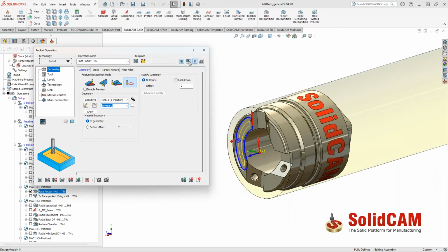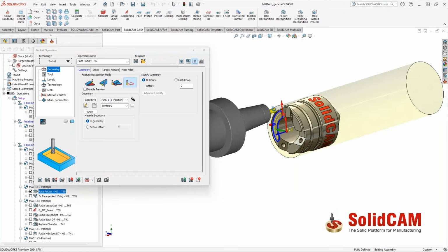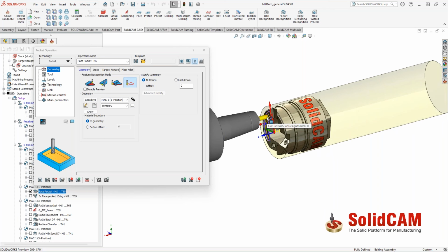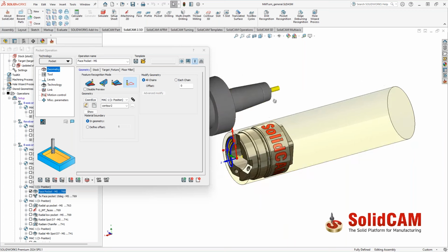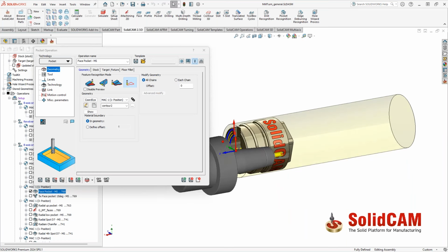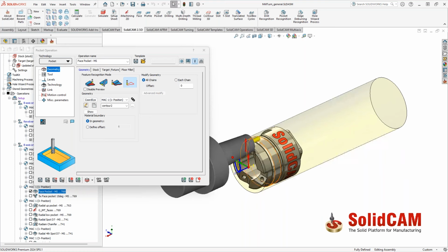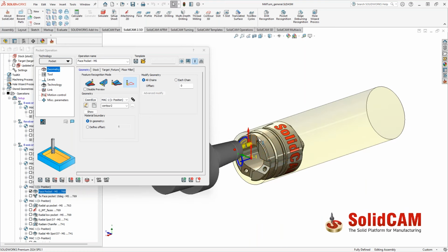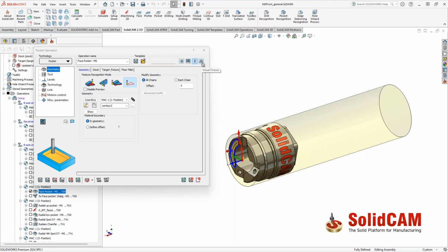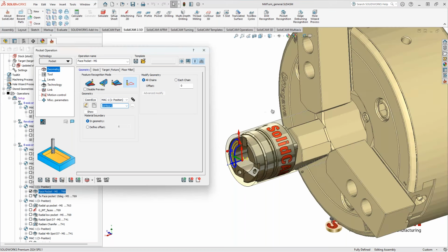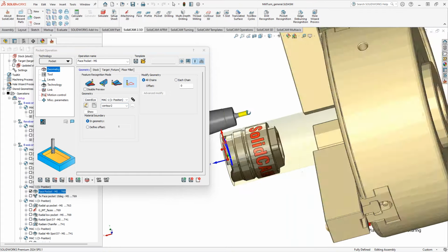What we always had here on the top is the visual tool, the 3D tool inside the SolidWorks environment. So you can move your mouse and you can see your tool itself. Now, very commonly when you're defining your project with fixtures that you're pulling from the toolkit library, you don't see the fixtures. We are taking them into account, but mostly during part programming you don't see them. Now in 2024, we added here a new icon called visual fixture. Once you click it, you're going to be able to see it.